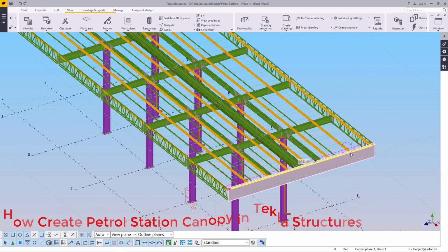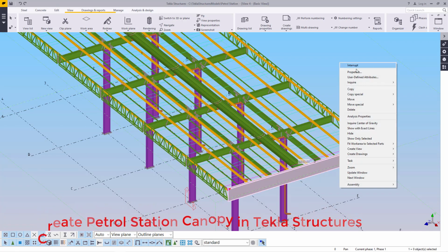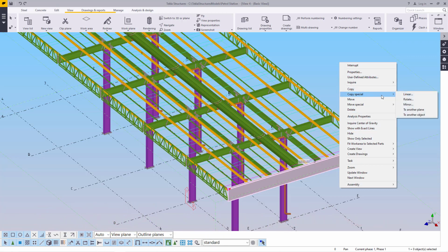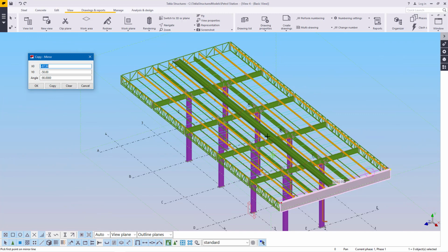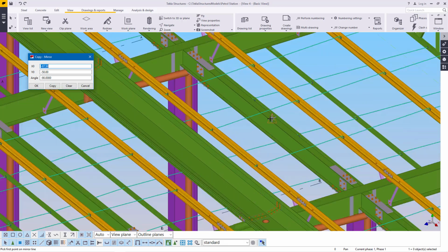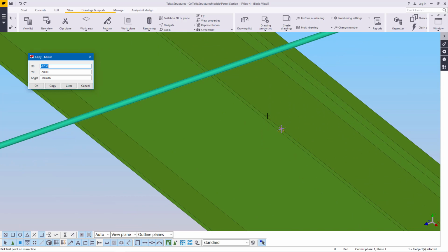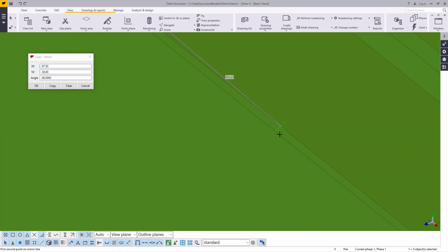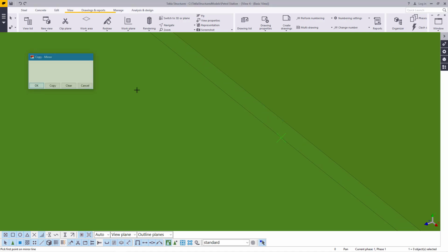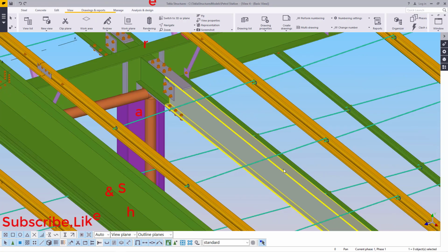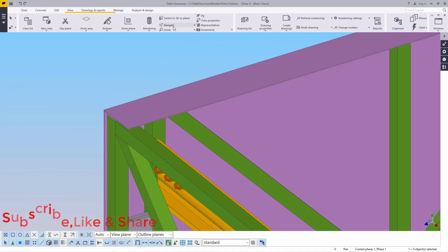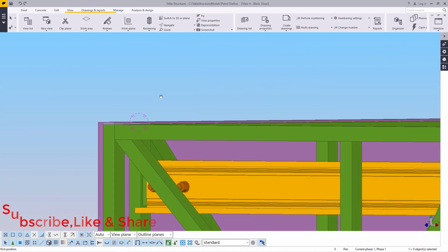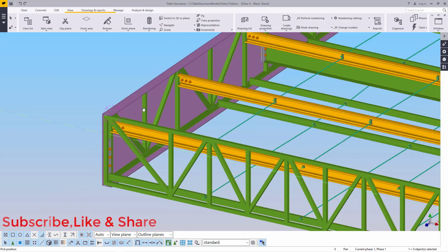We'll define a mirror line for this. So I'll right click once I've selected on that, and come to special copy and come to mirror. So I'll select the middle point of this structure, which might be here, which not might be here, it is here, and I'll snap on that and go all the way to that bottom end and click copy and try to see whether this will be copied to the other end. And actually it has been copied to the other end, in the right position. So this is how it looks.